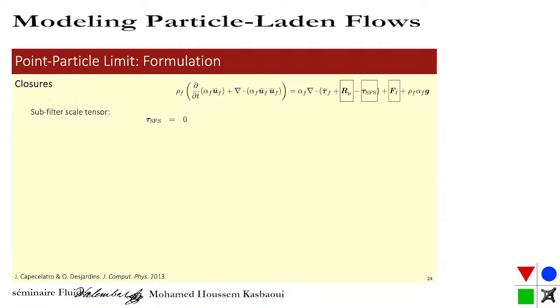Now, you have these closures to determine. The first one is the subfilter scale tensor. In a lot of these methods and simulations, people will assume that the subfilter scale tensor is negligible. So let me try to argue why that is.